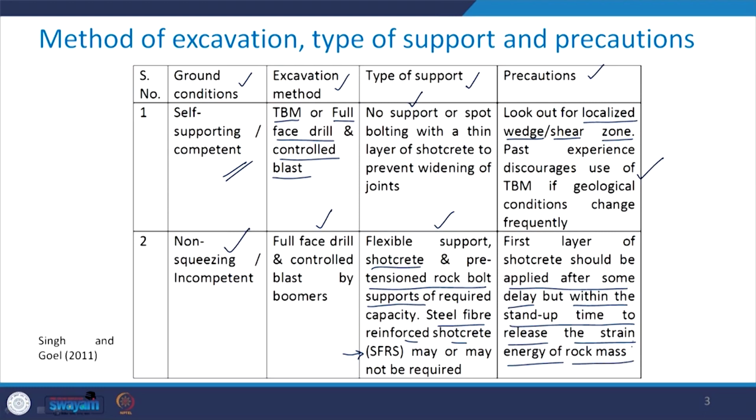So, the moment this excavation takes place, we need to wait for some time so that this strain energy of the rock mass is released. But we should not wait long and should provide the support system within the stand-up time. So, this is the precaution that one needs to keep in mind if the excavation is taking place through non-squeezing or incompetent ground.